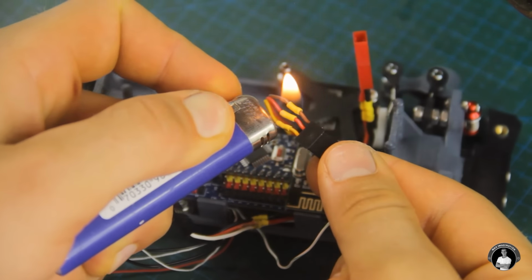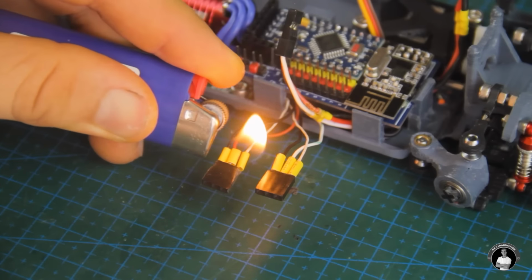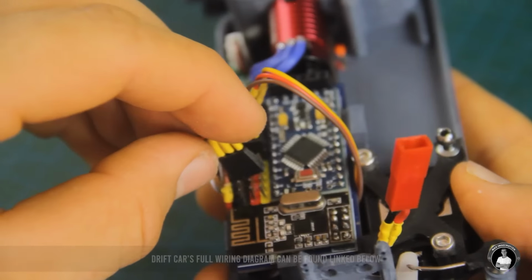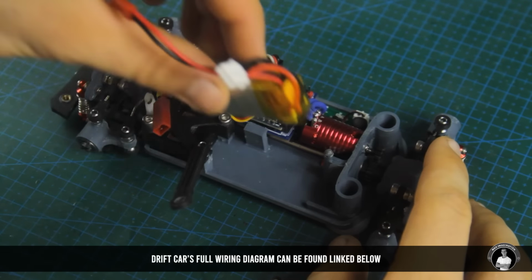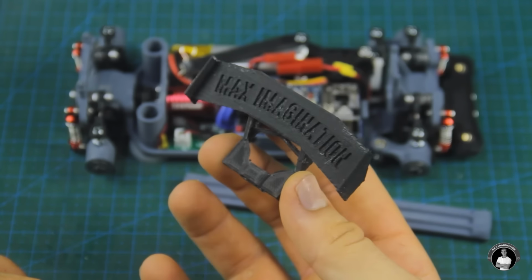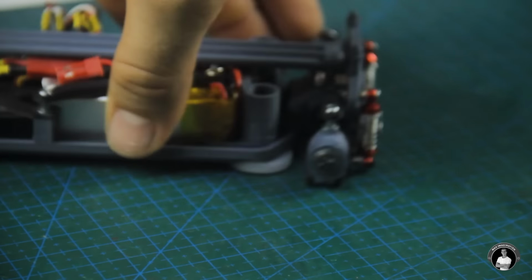To wire it, we'll first give the appropriate pin headers to the sets of wires from each module, shorten any if needed, and then plug these into the receiver's headers, starting with the ESC on channel 1, servo on channel 2, then the LEDs and the humidifiers connect to any channels from 5 to 8. Keep in mind that you can find the car's wiring diagram linked with the other project files in the video description. Next, we can mount the 2-cell 500 mAh LiPo battery held down with the clip and body pin. Then for both looks and stability, let's install the car's tail wing and top supporting bar, which prevents the chassis from bending.